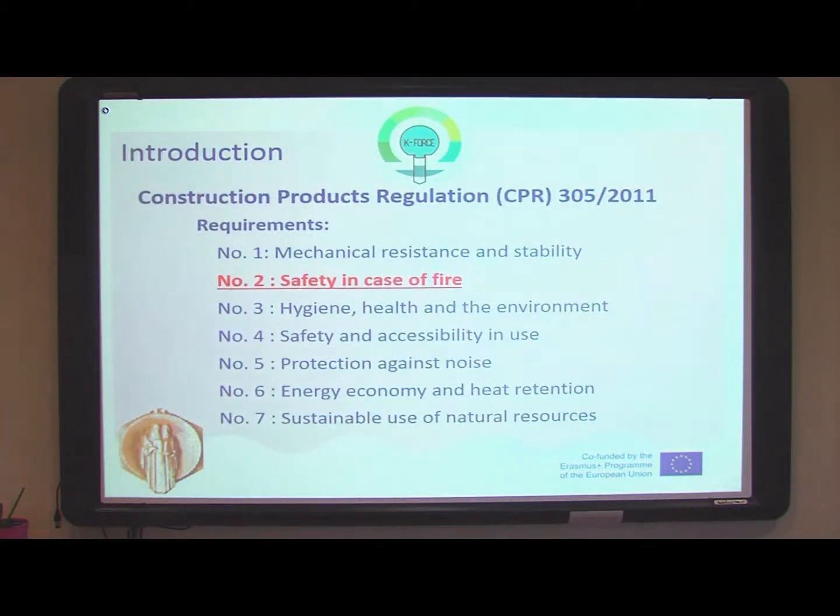According to the Construction Products Regulation 305 from 2011, the structures have to fulfill not only the basic requirements regarding the bearing capacity, stability, and serviceability, but also the requirements considering the fire safety of structures. Other requirements are hygiene, health and environment, safety and sustainability in use, protection against noise, energy economy and heat retention, and sustainable use of structural resources.